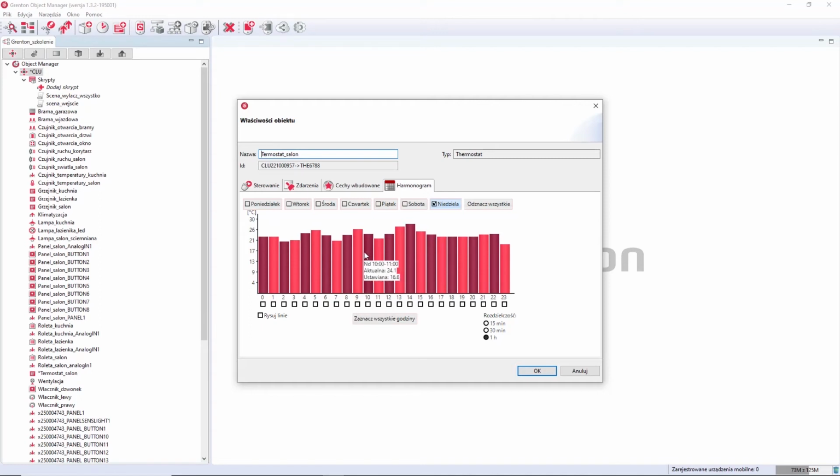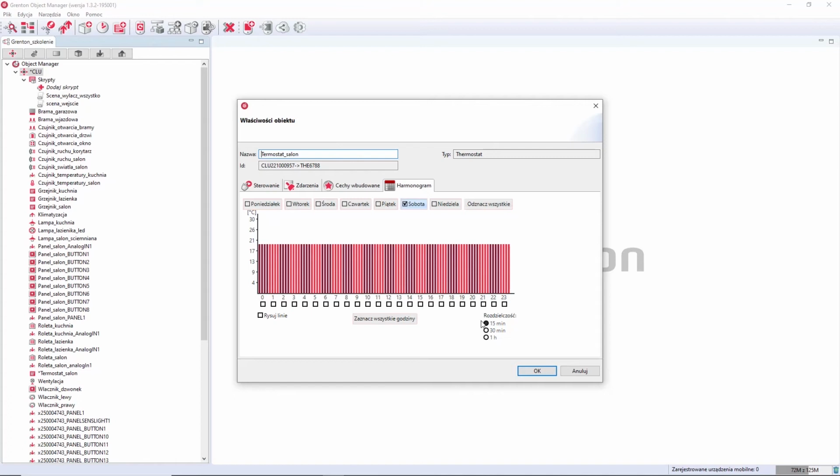Of course, I set this temperature now, for example, but you can do it more precisely. You can set it for each of the days separately. You can also set temperature for several days in groups. For example, you can select several days and set the temperature here for all those days. You can see now what it looks like. The temperature can be set in resolution every 15 minutes, so you can very precisely determine at what hours what temperature will be set in a given zone.